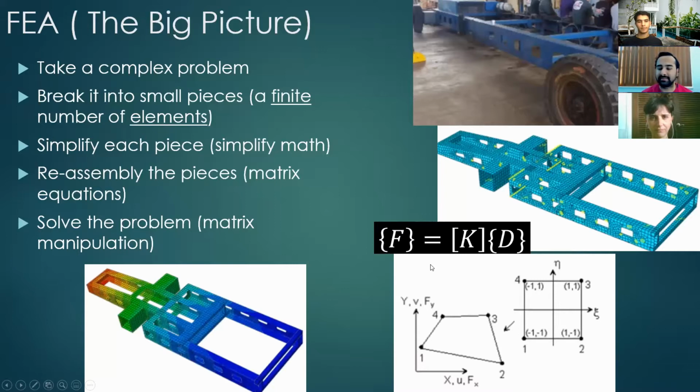And mathematically, what this means is that you know what the forces are on your object, so you know where the loads are, what part is being constrained, and you know what this K is. K is your stiffness matrix, and what goes into the stiffness matrix is material properties, so you know what parts are behaving linearly, what parts are hyperelastic, material information about your model. And what you want to know is, what's the relationship between the forces and the stiffness in terms of the displacements in my model? And that is what you're trying to find. The way you do that is you invert this matrix and isolate this D. And that will tell you this part of your model is going to displace by this much, the stresses are highest over here, and so on and so forth.